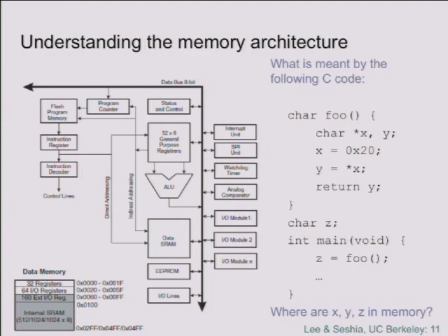That's actually a really good question. The question was, why don't we put it in the program memory? Someone want to field that one? Yeah. It couldn't be written to if the program memory can't be written to, but this is a flash, so we can write to it.